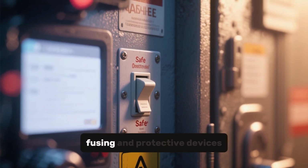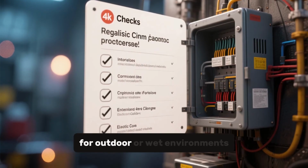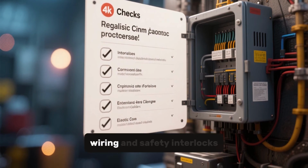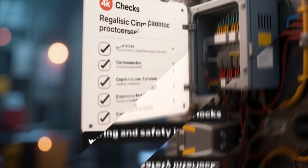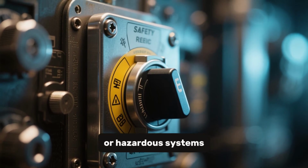Provide proper fusing and protective devices. Use enclosures and IP ratings for outdoor or wet environments. Follow local electrical codes for panel wiring and safety interlocks. Use safety-rated, redundant designs for life-critical or hazardous systems.